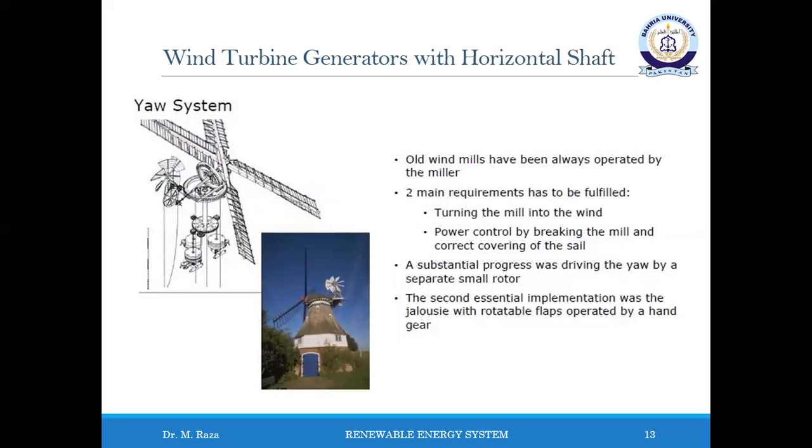In contrast to the modern wind turbine, the old windmills needed the permanent attendance of a miller, who was not only responsible for milling but also for the safe operation of the windmill. The main tasks in windmill operation were adjusting the windmill rotor to the wind direction, lifting or reefing the sails according to the wind speed for power control, and braking the rotor early enough when a storm was growing. Only the Western mill was the first type without need for an operator.